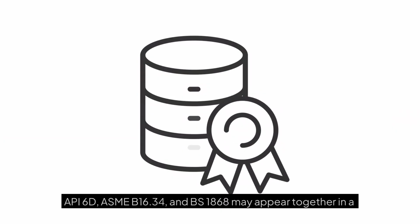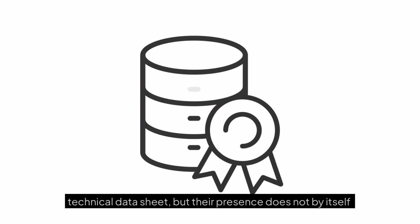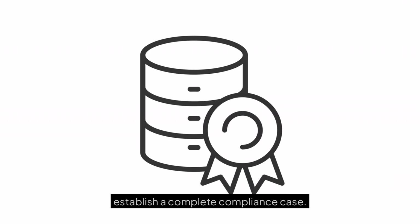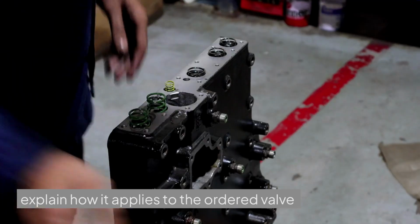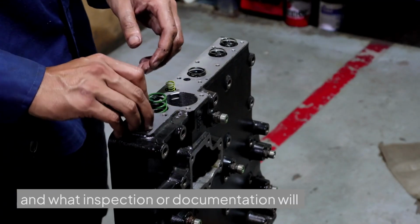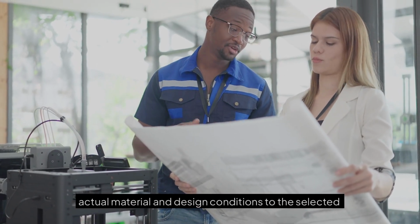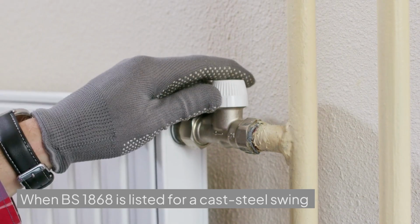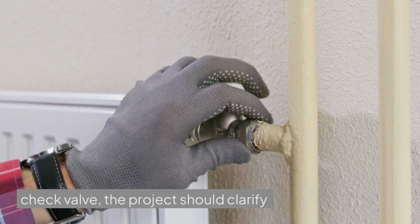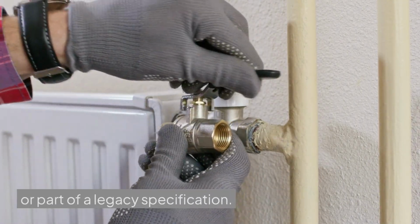API 6D, ASME B16.34, and BS 1868 may appear together in a technical data sheet, but their presence does not by itself establish a complete compliance case. When API 6D is listed, the supplier should explain how it applies to the ordered valve and what inspection or documentation will be supplied. When ASME B16.34 is listed, the review should connect the actual material and design conditions to the selected class. When BS 1868 is listed for a cast steel swing check valve, the project should clarify whether it is the governing design reference, an additional project reference, or part of a legacy specification.